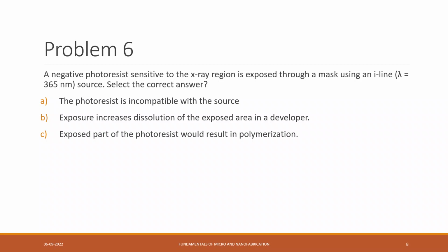In positive photoresist, the exposed part becomes soluble, and it will then be etched with the help of some material, acetone or something. In negative, the exposed part becomes solid, insoluble. And the rest of the part can then be etched and the pattern can be formed.